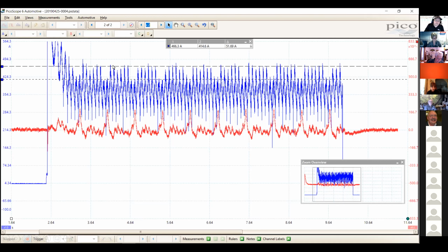If you look at the overall current, I averaged my peak currents to right around about 460 amps. The problem should be very, very obvious to you that as I go up on the compression stroke and the current increases to the starter and then drops and current increases, I have 2 cylinders in a row that are producing 50 less amps of current when going up on the compression stroke. And you're saying, Adam, you've got 2 cylinders that, at least from a relative standpoint, don't have as much compression as everybody else. That's right.